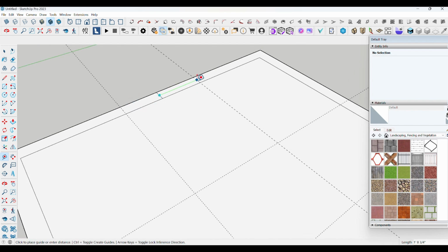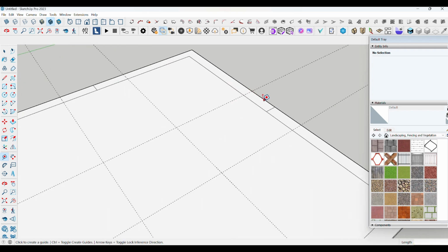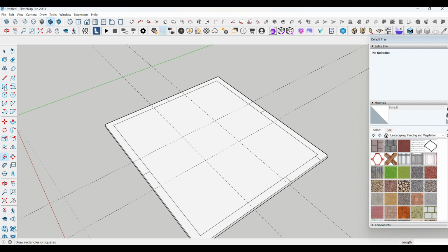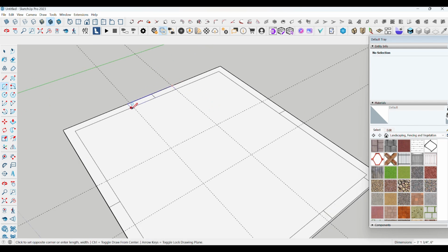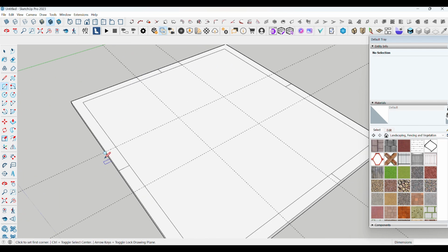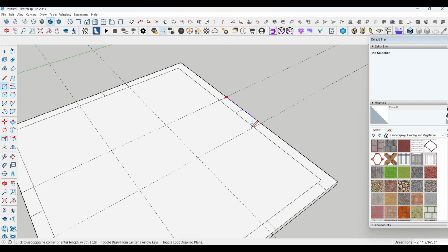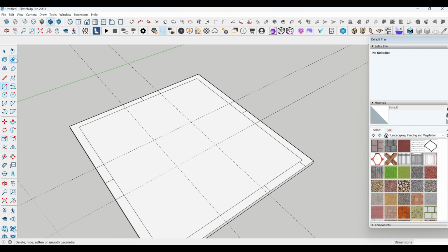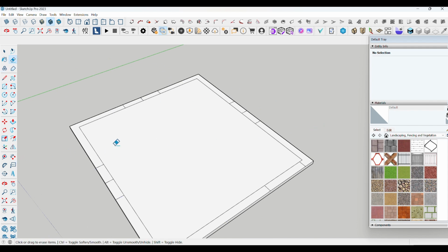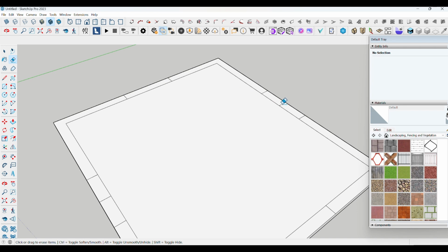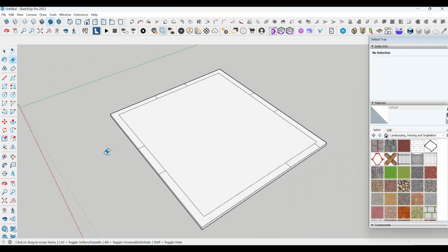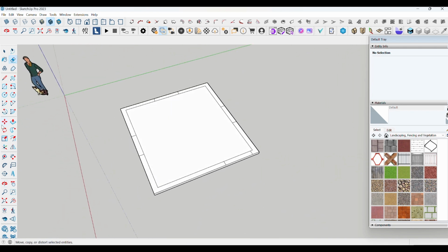It doesn't matter how much size you take. It is not compulsory to take 1.5 feet. You have to think about your standard, whatever dimension you want to create for your project. Accordingly you can take 3 by 4, 4 by 5 or 5 by 6 window size, according to your project. I have again created rectangles for all the windows, and now I'm going to create a particular opening for the windows and door.